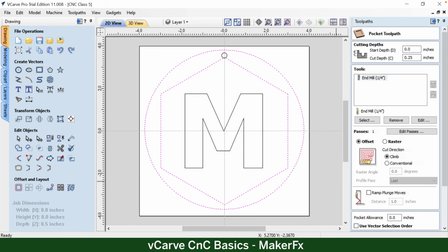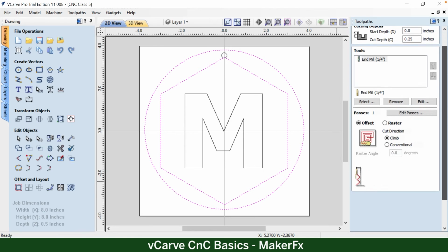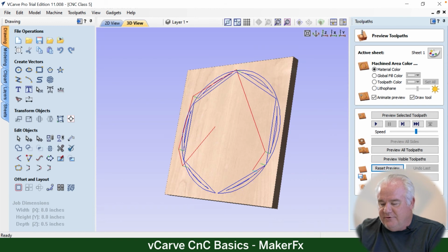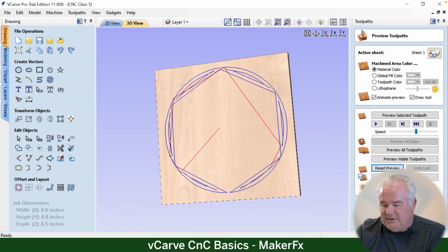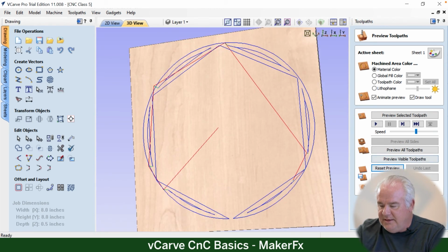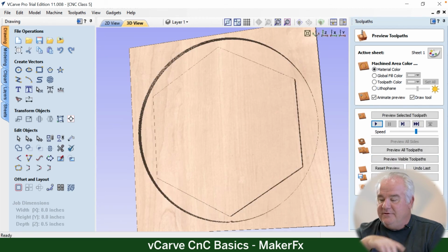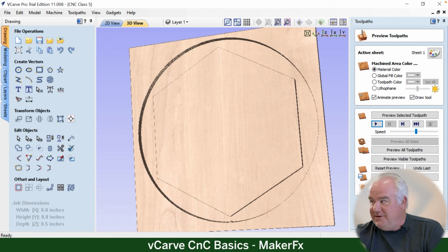But you can also go back into the toolpath because I want to get to the visualization. Click calculate. Reset the preview. I'm going to turn this back so we can see it and zoom in a little bit. And then preview that toolpath. Whatever the last recalculate you did is what's going to be used to create the G-code file. Okay, and we can't create the G-code file here. We can only create it on the laptop.